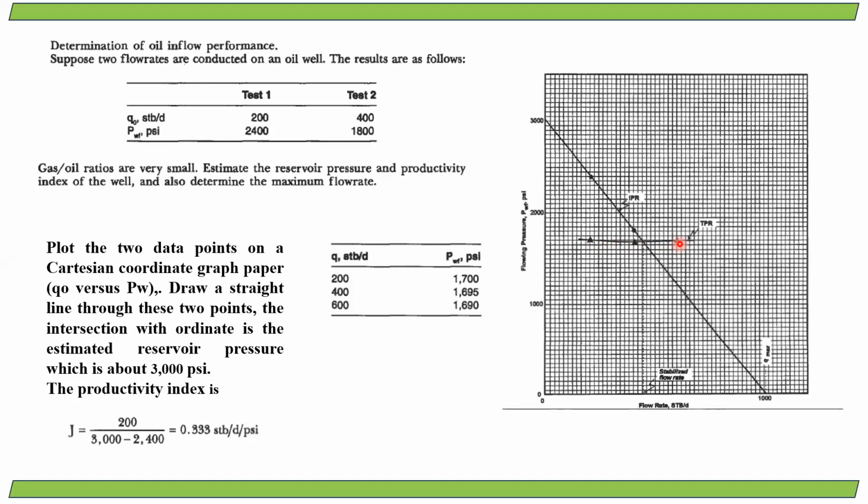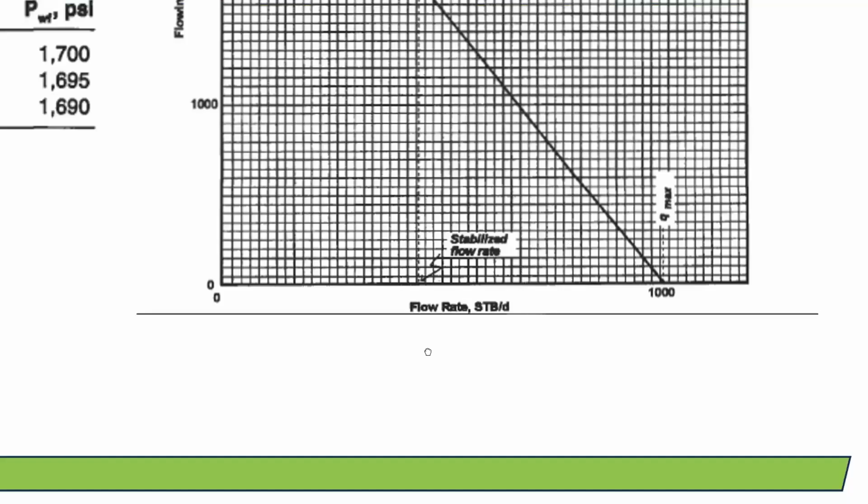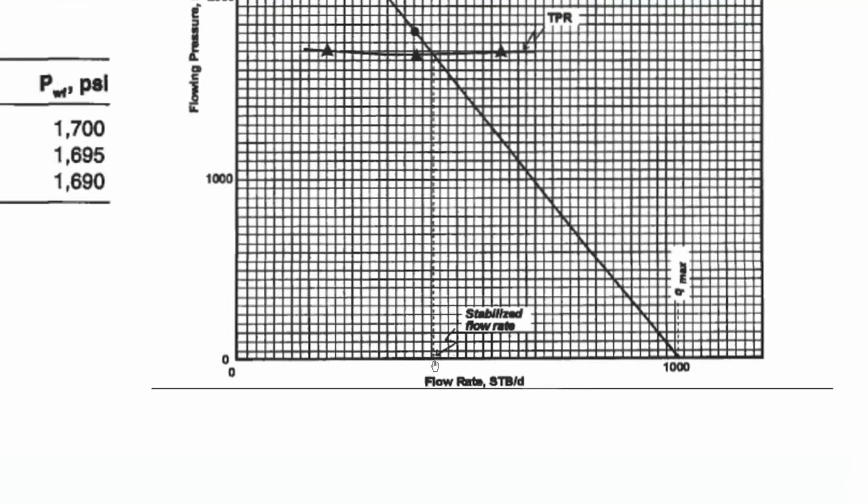So we are just taking IPR after tubing adjustment, and we are extrapolating on IPR, and we are seeking for the interception, and we are projecting from that interception towards your x-axis to get the best flow rate for that particular adjustment. So this is the one. This is what exactly I have done. So this is what exactly manually it will be done. Right now we have done with Excel.